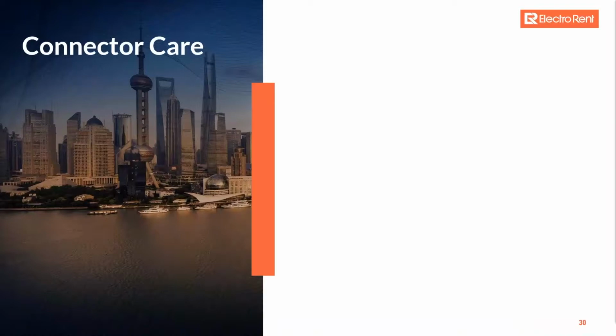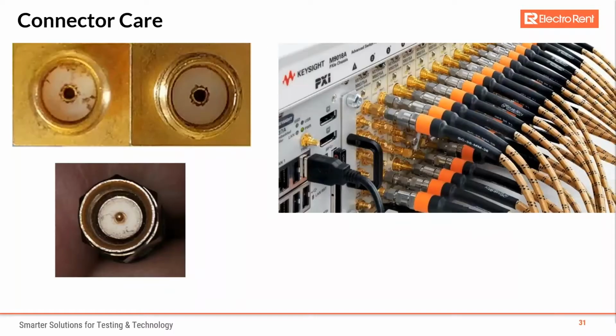So, connector care. Connector care is something critical for all of us that sometimes some engineers just don't take into account enough nowadays, or even when I was starting out, I remember. Connectors, adapters, and calibration standards, particularly in the millimeter wave frequency range, are very expensive. Although connectors eventually wear, with proper knowledge, care, and technique, you can easily maximize the accuracy, repeatability, and useful lifetime of these connectors.